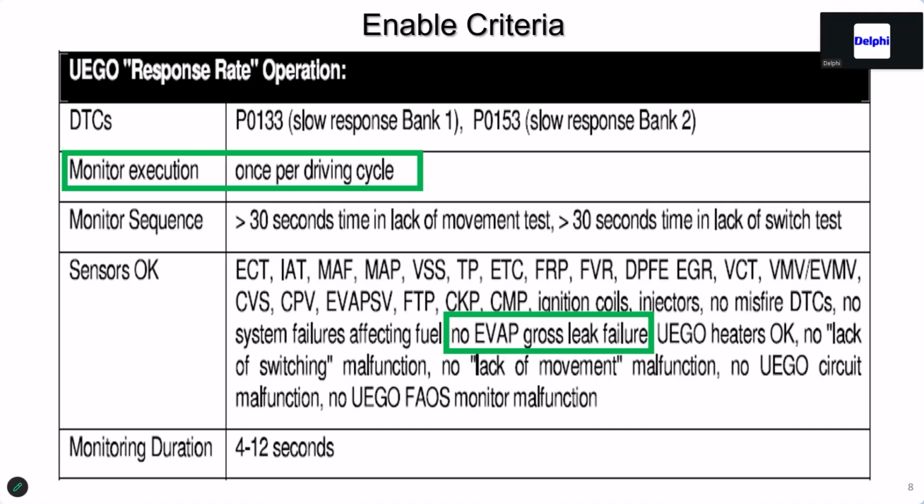Okay, and the last one at the bottom is important. When we start running monitors, drive cycle tests, the tests themselves don't take very long. I've seen 40 seconds. I've seen a minute on some. I've seen some Toyota early EVAP systems take an hour. But as a whole, when we run monitor tests, the actual test itself is only for a very short period of time because they don't want an intrusive situation where the customer is going to feel what's going on. So they're going to take a sample. In some cases, they might only need 1 or 2 samples. In other cases, we're going to talk throughout the classes, they may need multiple samples. And this is why you've done everything right and you're wondering why it's not completing.